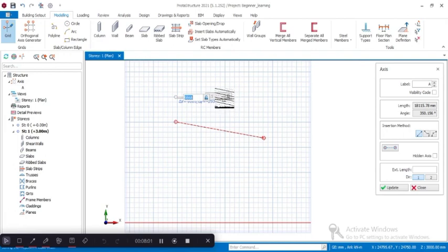F2 is clicked and you can see you can specify the length you want. Press tab to cycle to the next input, angle. Then if a value is entered in the text box, the related parameter will be locked. You can unlock by pressing escape or pressing the lock icon on the right of the text box.